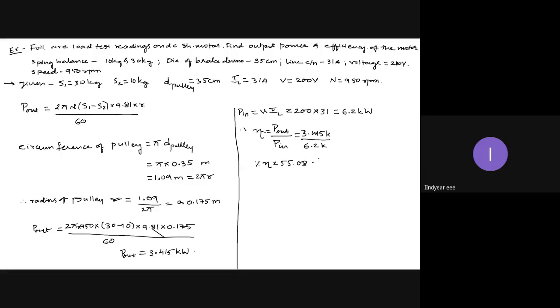So when do I use losses to find the temperature rise? I use losses to find the temperature rise in all the indirect methods of testing, where I am not directly connecting the load to the motor, but still I find certain methods of testing through which I can know the performance of the motor. In such cases, by observing the losses value, I can calculate the temperature rise.